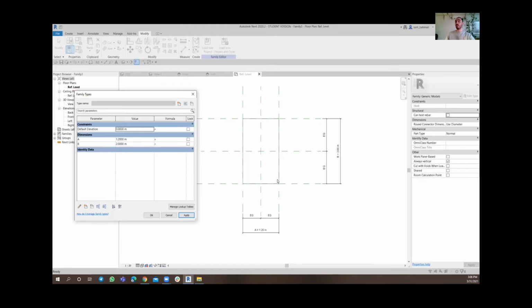That is essential, so it can be the base of the table plate here, right? Then we have to start defining the parameters. Also, it is super important to first define an equal dimension that way, so then we will be able to order Revit to always change the size equally from both sides.